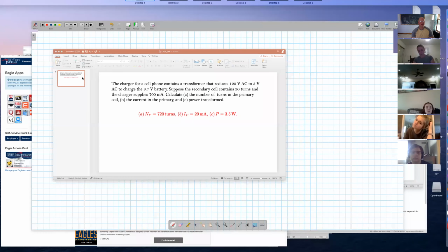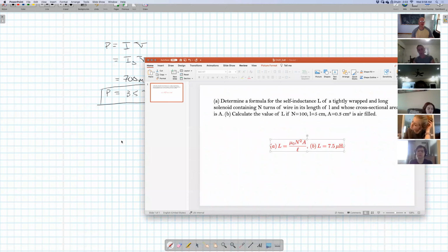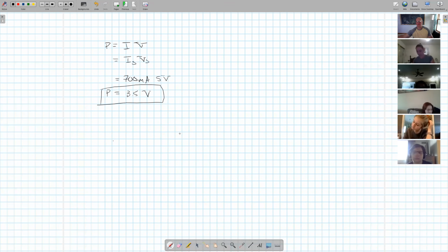So this is the main use of EMFs, at least inside of things that you're mostly familiar with, which is the transfer of energy from the power company to your house. This is actually why we use AC. The point of using AC is to use transformers, which allows us to go to a much higher potential. That higher potential allows for less power loss because the current is much smaller and the potential is much greater, which minimizes the amount of power being lost as it's transferred from the power company to your house. This is actually the real reason why we use AC.